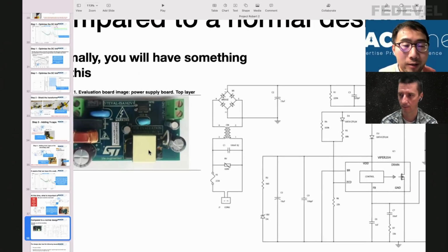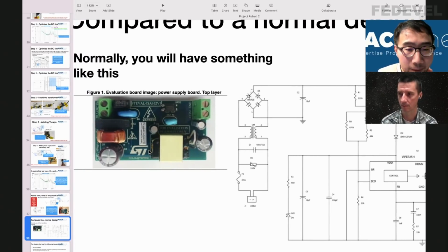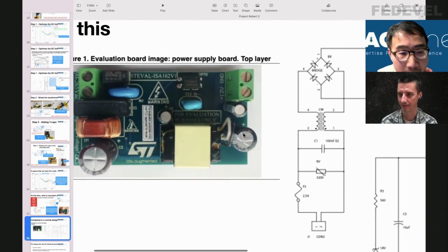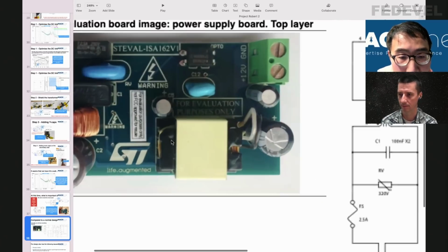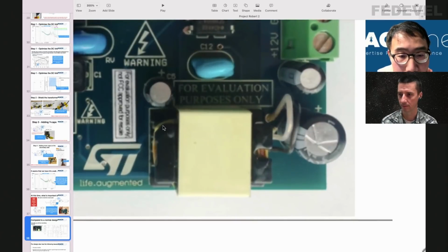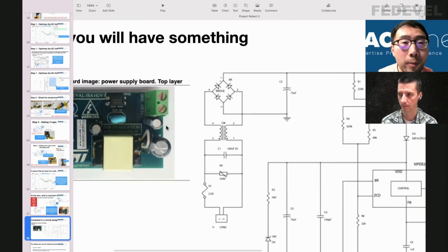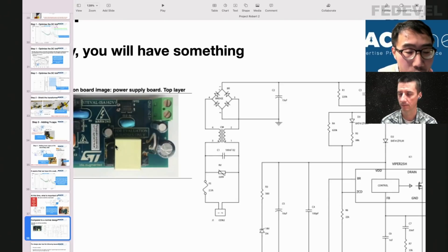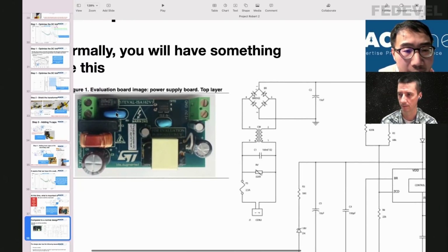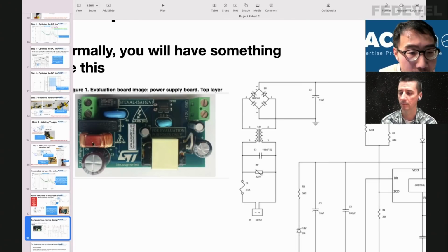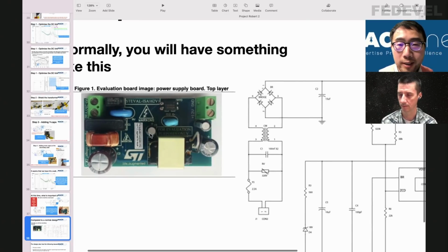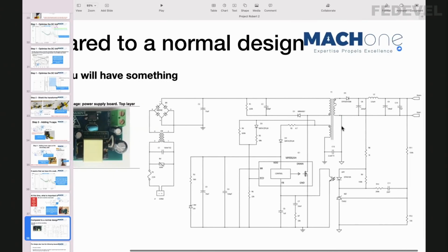Okay. So this is a demo board from ST Electronics. I found it online, and you can see the quality components they use. Did you see that they have a few capacitors? 1, 2, 3, 4, and then you can see this is the transformer. If you look into details, I'll zoom in. Did you see this thing here? It's what we call a belly band shield. So it's a shield on the transformer, same as we try to apply. I think this must be an X cap as well, or maybe a MOV. I can't see from this angle. And then they have a common mode choke, as you can see. All good quality stuff.